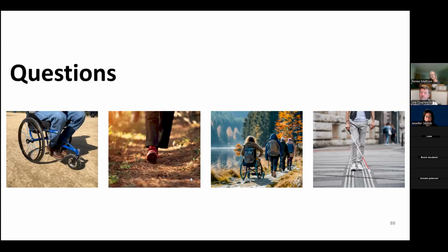We had a trail in the South Bend area where they wanted to use crushed limestone, and the designer had really good experience with it. Crushed limestone is used on all of the secondary trails through the Notre Dame campus. But in the location where a segment of the trail was installed in the park, a 100-year type flash flood came through and washed the whole thing out.